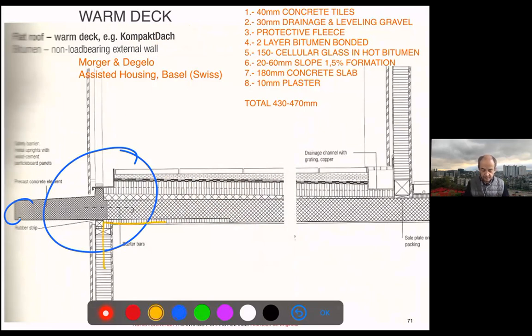Again, we have problems with the insulation. So the thermal bridge is there. And probably this was what we were saying before. So the problem is the thermal bridge. There's a point in which a few years ago, we had enough insulation with this extension, because concrete is also insulating. So if you have 1 meter of concrete, then you have an acceptable insulation. But now with the zero energy buildings, we need to have maybe 3-4 meters. And then the full room is with insulation, and you don't have the advantages of the thermal mass of the concrete anymore.